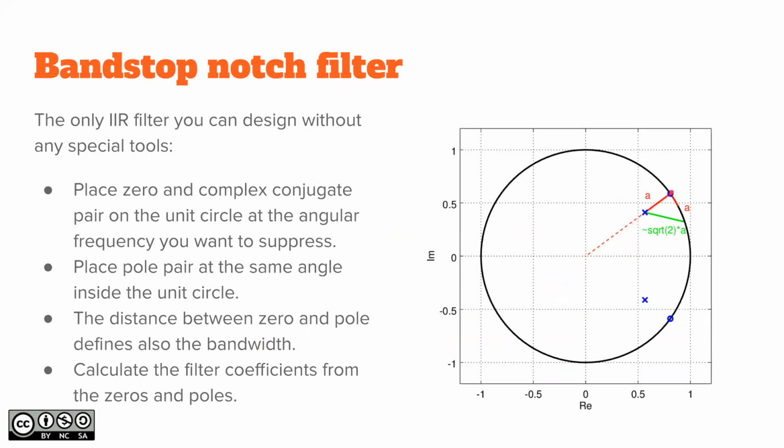And then you put a 0 on the unit circle. It gives you the maximum attenuation where the amplitude response goes to 0. And then you put some gain on the same frequency by adding a pole on the same angle. And then you adjust this minus 3 dB point by moving the pole close enough to the unit circle. I will show you that in the...